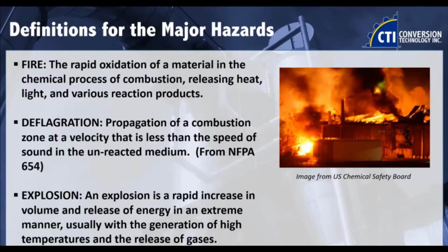One thing to think about, and I just want to make this a little clear, is I am not only looking at inside of equipment. One thing that I particularly emphasize during a DHA that I'm conducting is I like to look at housekeeping, because I think that's one of the hidden dangers of combustible dust.